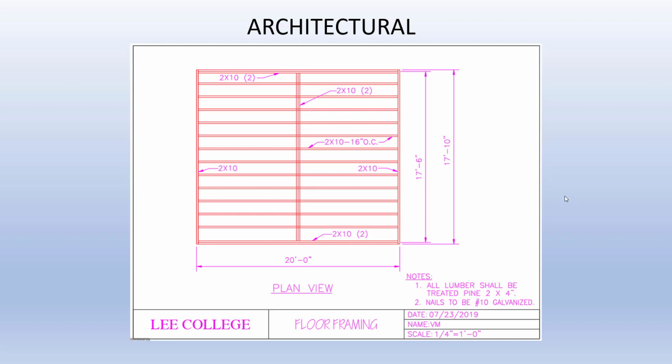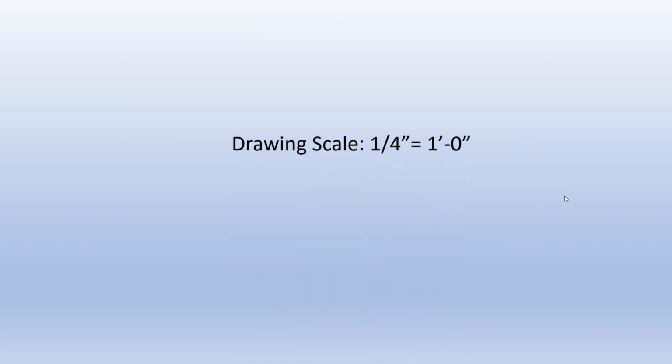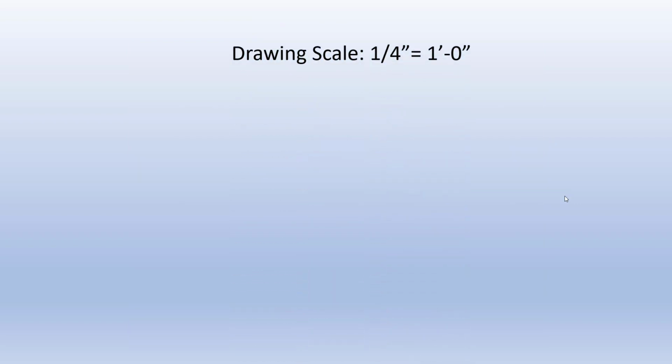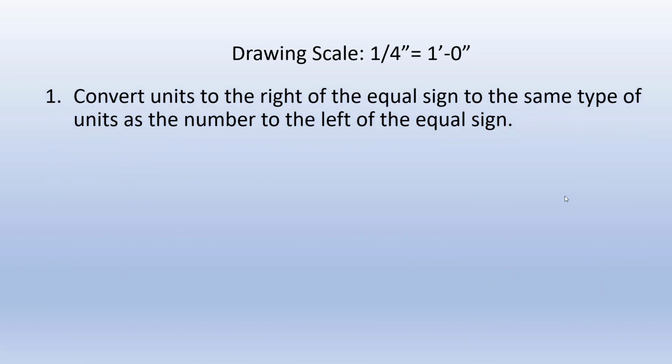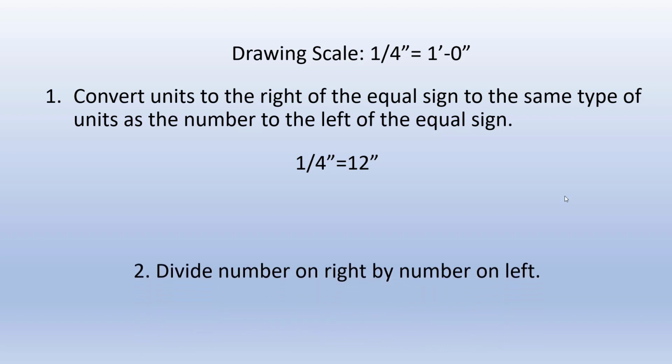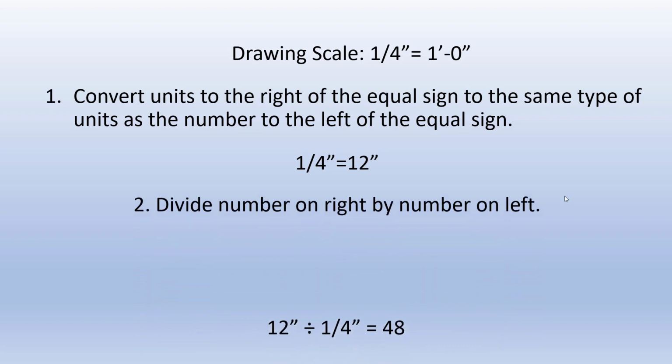Let's use our scale factor calculation process to find the scale factor for this drawing. First, we convert the units on the right to obtain equivalent units. Then we divide the number on the right by the number on the left to obtain a scale factor of 48. So this would be the scale factor for this drawing.